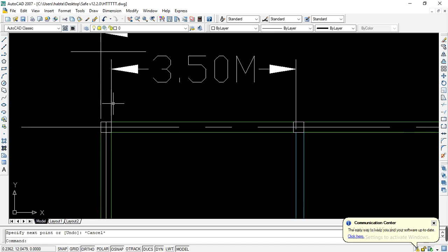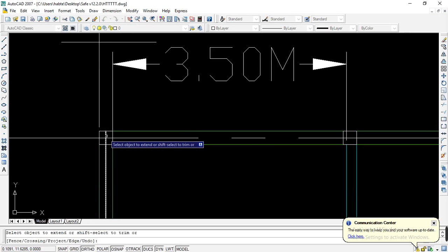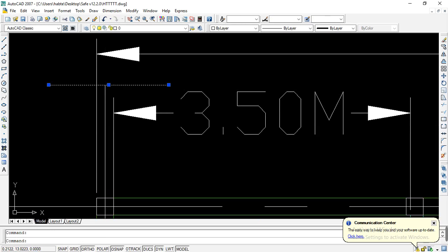So then after extending this object up to this, finally I can erase or omit this object because it's not functional anymore. So I'm selecting the extend symbol. Then after that, I gotta extend this one. Okay, good. Then after extending the object, I gotta erase this one.